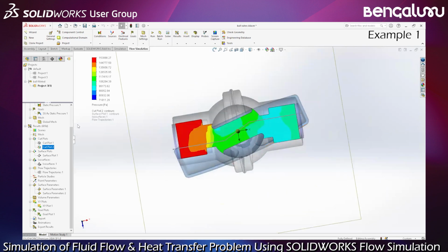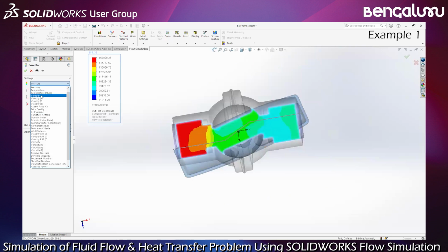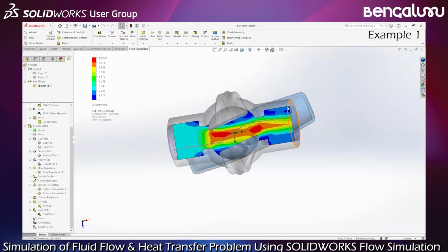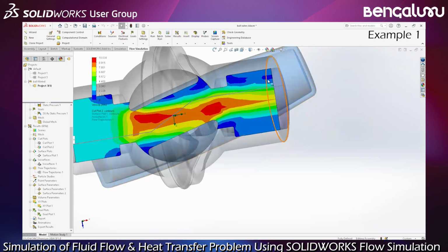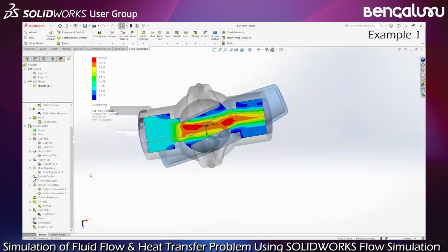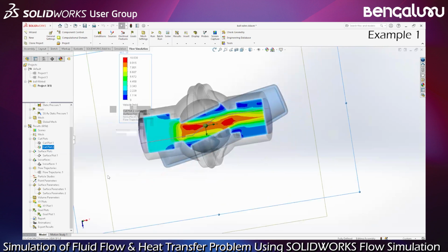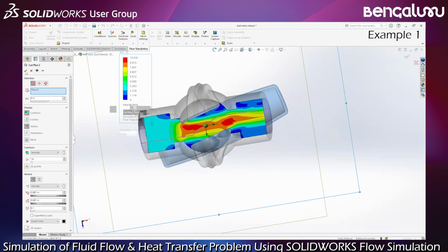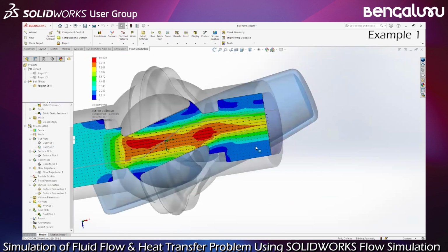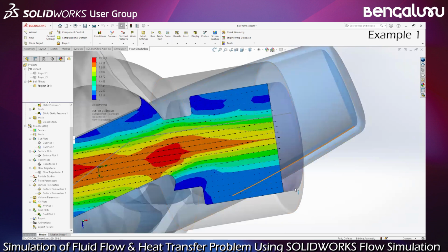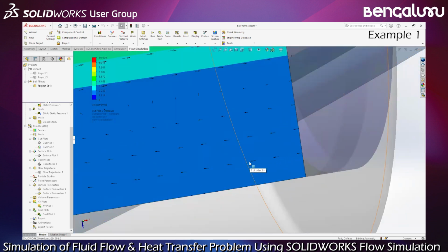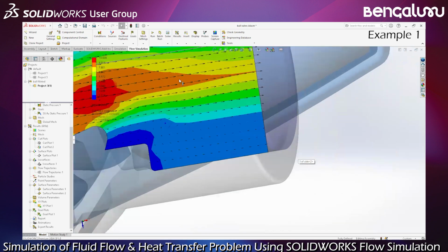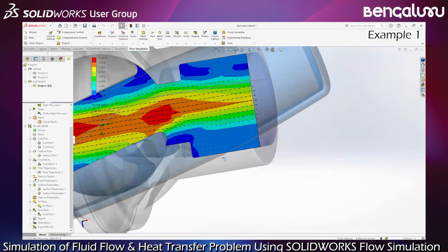We can see here. Let's switch to the velocity. Okay, you can see here that at the outlet it is not very stable. And we may look as well at the vectors. So you can see that, maybe due to the circulation, if I zoom here, at the outlet you have a part of the surface which results in inlet, which is supposed to have the full outflow. It's due to the circulation.